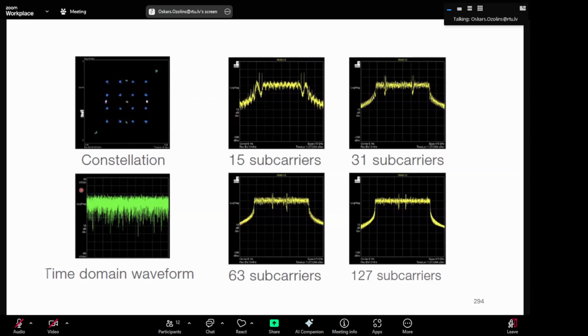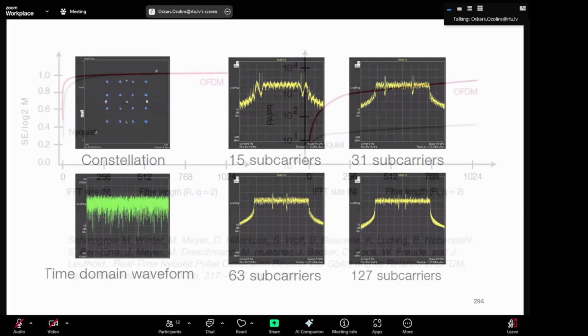It is widely adopted in radio systems, but in digital coherent optical communication systems, OFDM is thought to be too complex, because the implementation seems complex and these subcarriers are not that narrow. So what we can see is digital subcarrier modulation with wider subcarriers there as well.